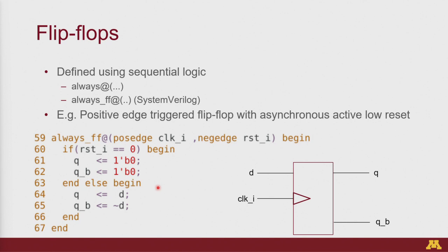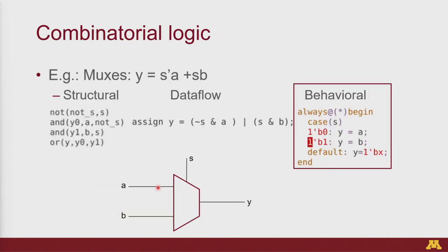What I meant was, the blocking statements within a combinational block will be executed in parallel, right? No, those will be executed in series, in sequence. That's the one exception I mentioned. Within an always block, it executes one line at a time. In that case, could you please go two slides back? I had one question. Here, yeah.